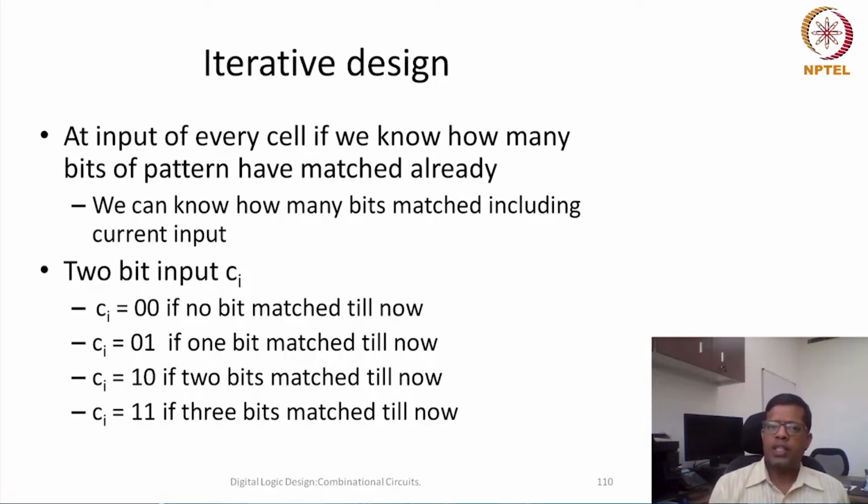Which particular information should I call 0 0, which should I call 0 1, 1 0 and 1 1? This is actually independent. It doesn't matter for design. For optimization, yes, there could sometimes be an advantage of one over another, but as a design exercise, it is more scalable to keep them in the order 0 0, 0 1, 1 0, 1 1, so that it's simple to write, and for analysis afterwards also.